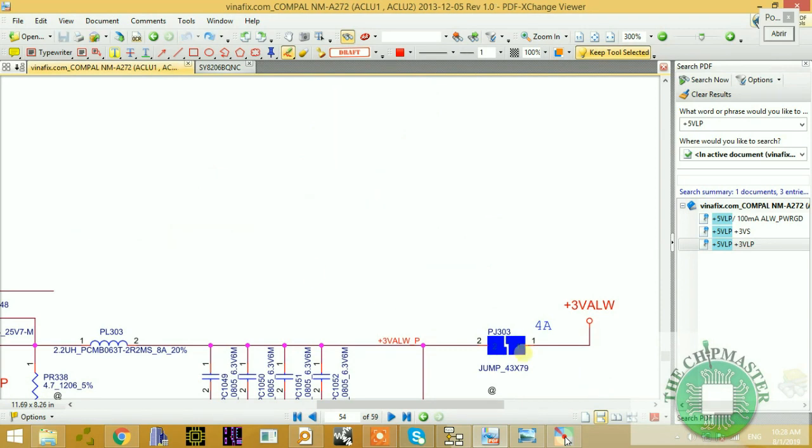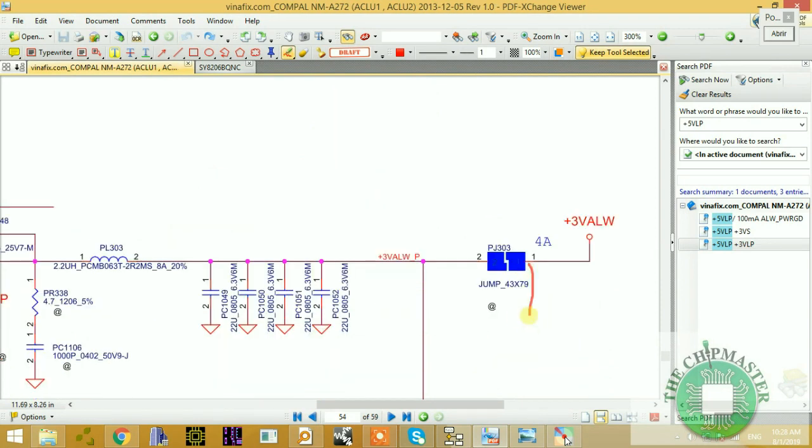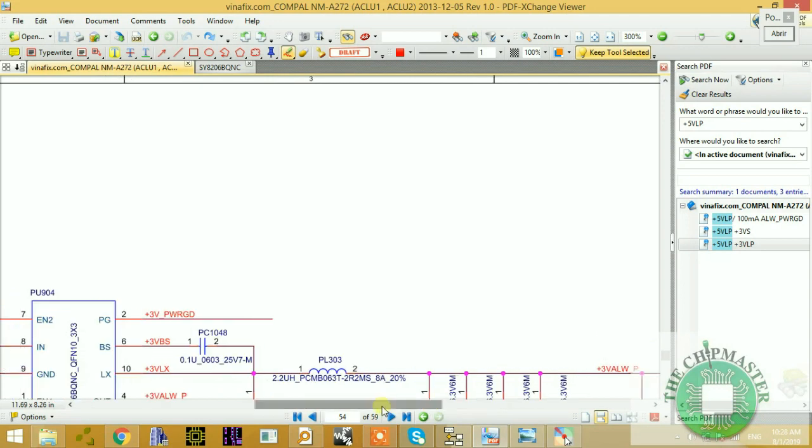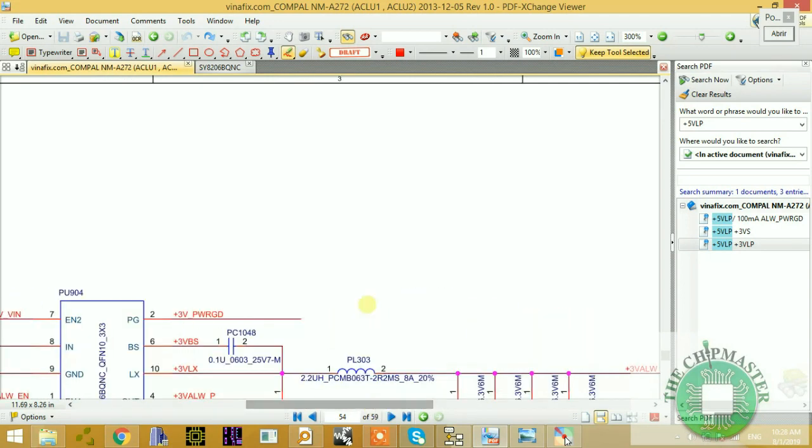Most times on other motherboards, there will be a filter capacitor on the outside that is connected to ground. That filter capacitor will be leaking, and it will cause the over voltage protection on the oscilloscope waveform. This is being taught in my PWM class. So I'll teach you all the tricks and nuts and bolts of a PWM and fault finding in 3 volt and 5 volt. This is just a timing section I'm teaching, right?